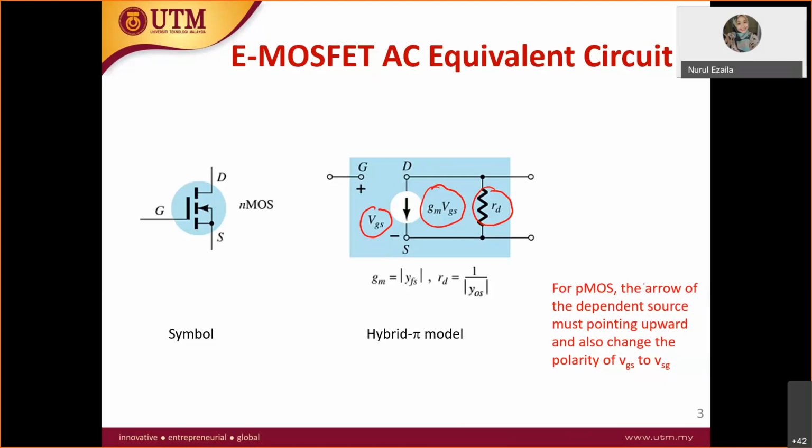So this is how it looks like. Okay, so this is for the N channel. So the current is pointing down. Why is the current pointing down? You have current ID over here. So this current ID goes from drain to the source. That's why the current is pointing down from drain to the source. Okay, if you have PMOS, this current will go up, from source to the drain, like this. But now we are talking about NMOS.